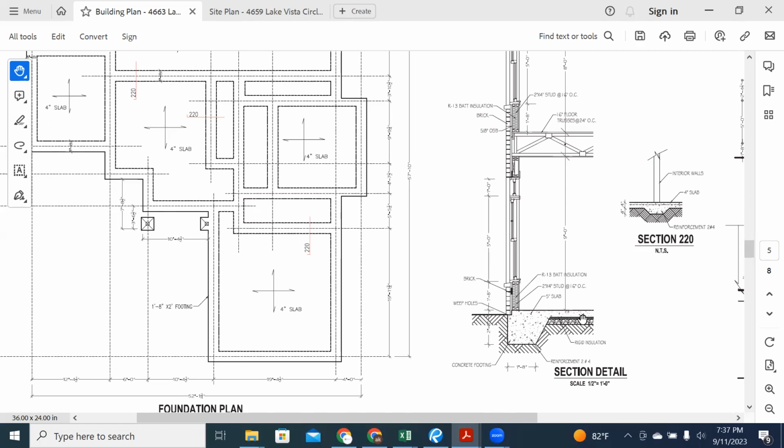The thickness of it is 6 mil. And if you go any thinner than that, I don't think they pass you for inspection. It has to be at least 6 mil thickness. So we laid that over the gravel. Okay. And then we actually, in our case, we dropped the grade beam wires, rebar on top, because we had made sure that we had it dug this wide. We dropped the grade beam wires on top.